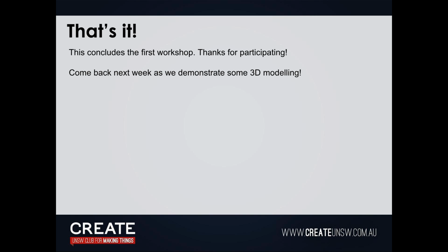To save time, I will just mirror that along multiple axes. So with the mirroring tool, we select these 2 curves, hit mirror, then select the mirror line, which is this vertical axis. Oh, there we go, that's one done.